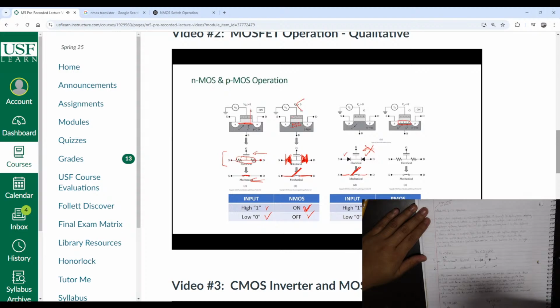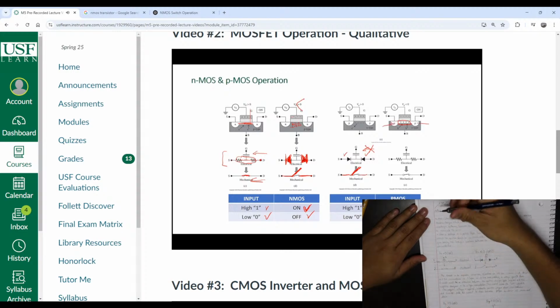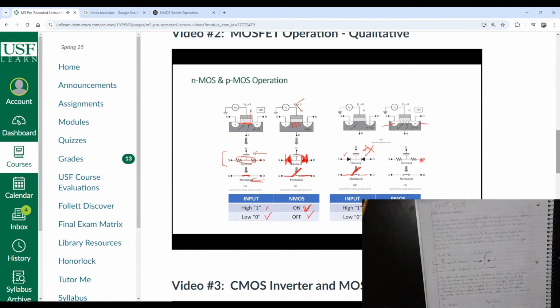And now we are connecting the P region here and the P region there with another P region in between. So the PN junction is no longer there. We no longer have PN junctions, but the middle region looks like a resistor. If you were now to apply a voltage between the drain and the source, you get current to flow from the drain to the source, and therefore your switch is closed. We've looked at the last case in our tables, where we applied a negative voltage on the gate of a PMOS, and we found out that the PMOS turned on.